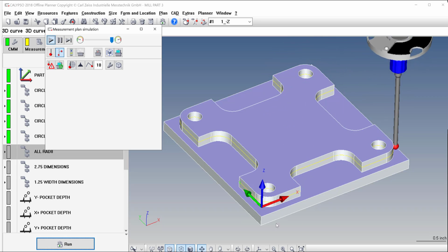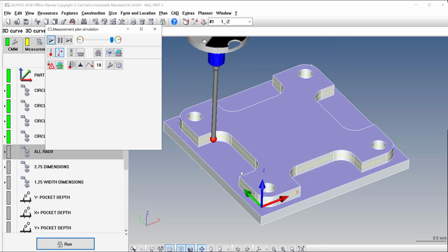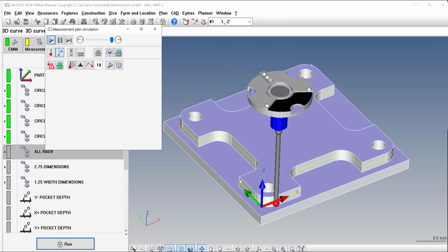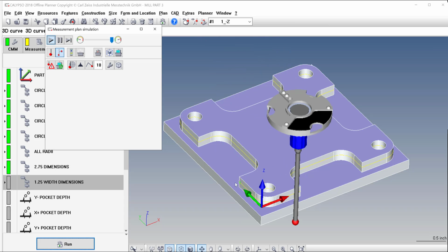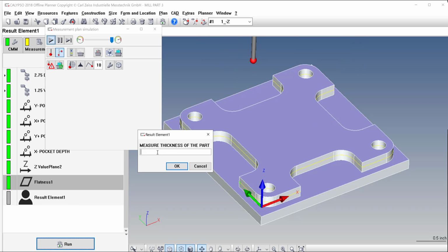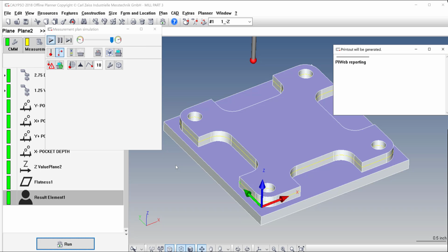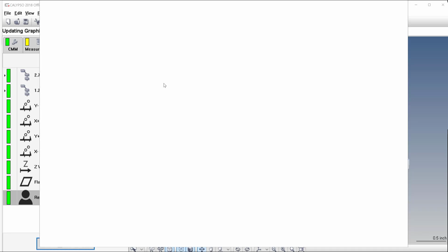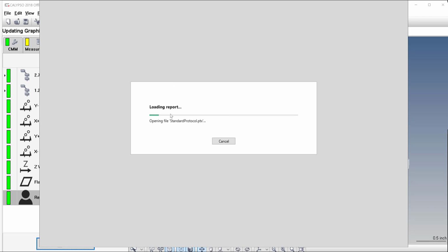And again, remember, we did get rid of the issues in the corners because the probe can measure funny there. So again, it's following that path, but those are eliminated from the inspection. So now it's just deriving the points. And it takes the 4, hops around, then again, it prompts us: measure thickness of part, 0.375, then hit OK, and that's the program.